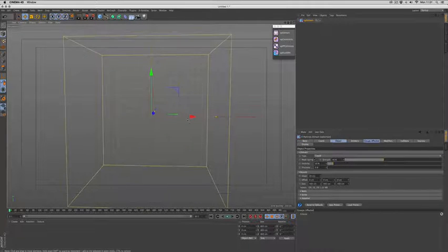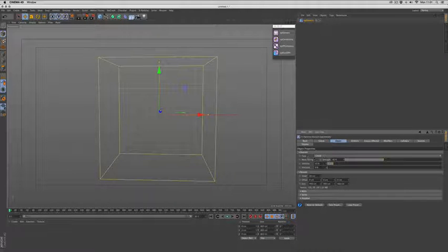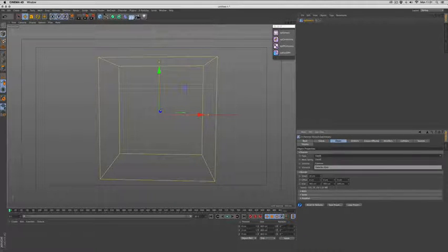By default the Xparticles domain is set to a 400 by 400 grid and to the liquids mode. If we look at the domain objects tab, we have type liquid, gas and particles gas. These do different things. Let's start with the liquids. First we have weak springs and a strength modifier. This lets you keep your particles together like a constraint.